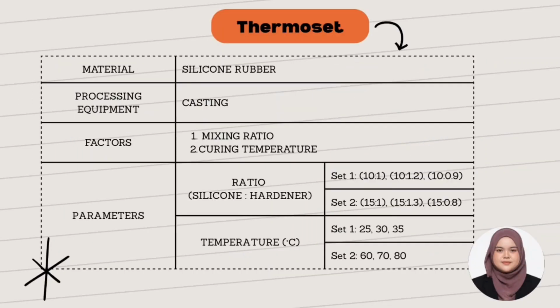Next, for the thermoset processing parameters, silicon rubber is used as the material, with casting as the processing method. Two main factors are considered, which are mixing ratio and curing temperature. For the mixing ratio, set 1 ranges around 10 to 1, while set 2 uses 15 to 1 with slight variations. Meanwhile, the curing temperature for set 1 is between 25 to 35 degrees Celsius, and for set 2, it ranges from 60 to 80 degrees Celsius.